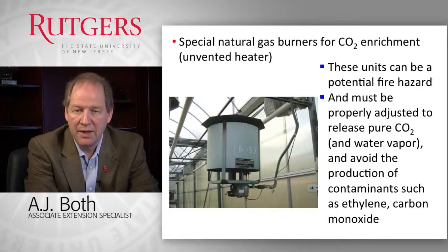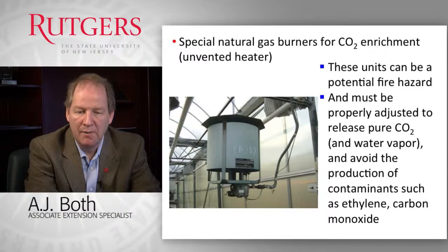We can also generate, as I mentioned, CO2 by a combustion process. We have special burners that are specifically designed to generate CO2. They obviously also generate heat. So enrichment of CO2 occurs in this case at the same time as heating, and that may or may not be an issue if you don't want heat at the time you want to enrich. But anyway, these units are able to combust typically natural gas very cleanly if they are well maintained and well adjusted, and then they can release CO2 into the greenhouse environment.